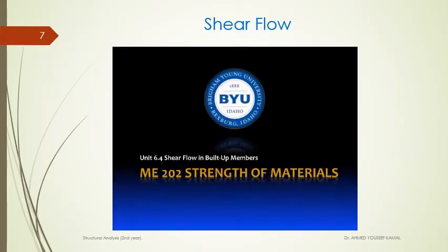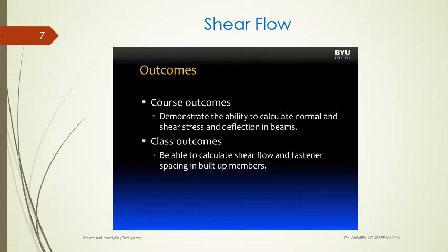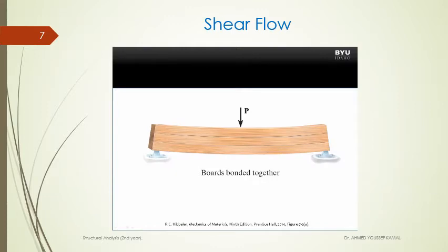Unit 6.4, Shear Flow in Built-Up Members. In this unit, we have focused on the course outcome, demonstrate the ability to calculate normal and shear stress and deflection in beams. In this lesson, we will focus on being able to calculate shear flow and fastener spacing in built-up members. Let's begin by considering this beam shown.